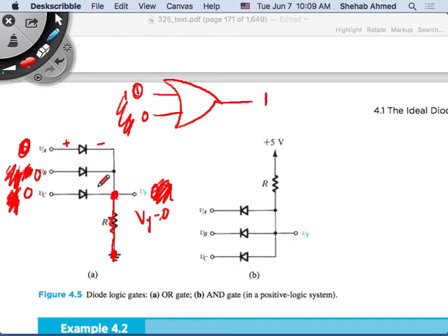Then you have what is called in digital circuits a floating point. You don't know what the value of the voltage is. You always have to define your voltage. That's where you as a designer need to make sure your circuit around the diodes is a good circuit. If you don't do that, then it's your mistake. It's not the diode's mistake. Blame it on the diode, yeah. So this is another application. We saw two different applications: one in the digital domain, one in the power electronics domain. Then we will see another application in the amplifier domain.